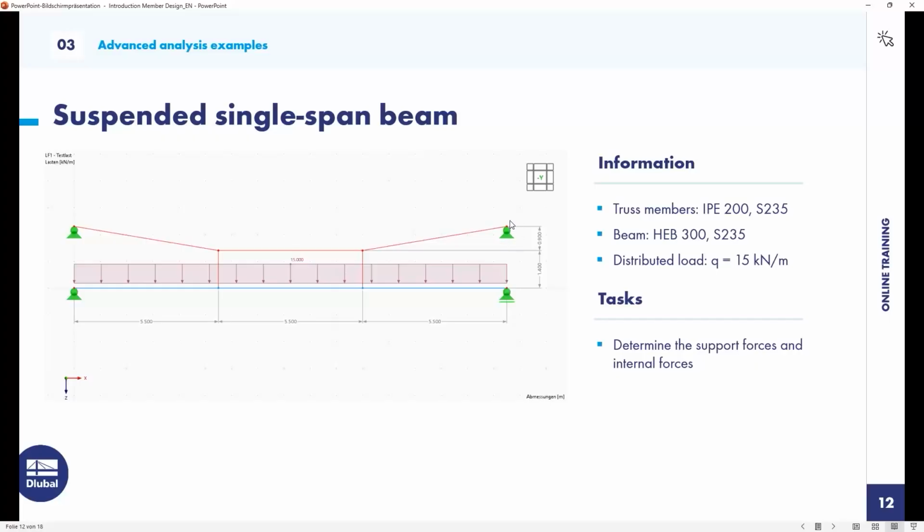And that is also necessary because if you imagine that this is like a rope, then you will get very decent tensions on this member. And if we would make the deformation in X axis free, then this rope would simply go to the middle of the structure, and the function of this support would not be there anymore.